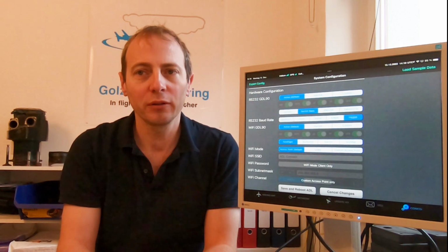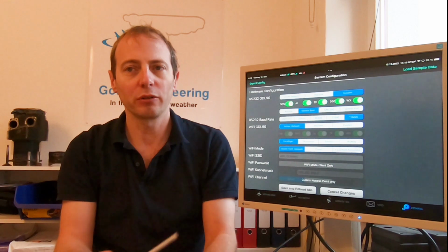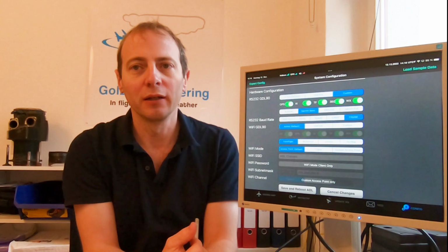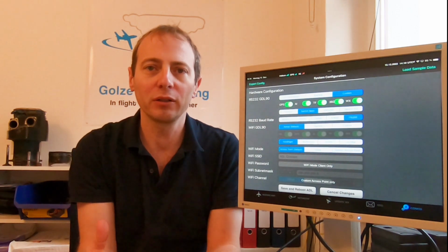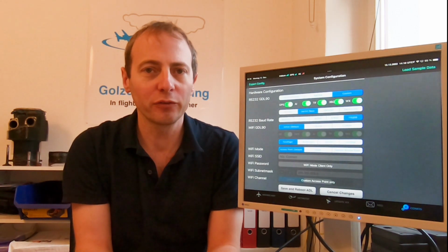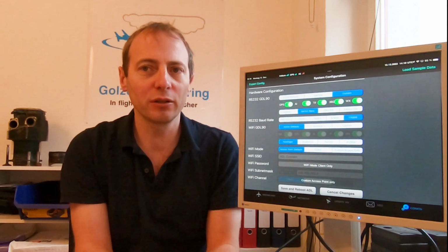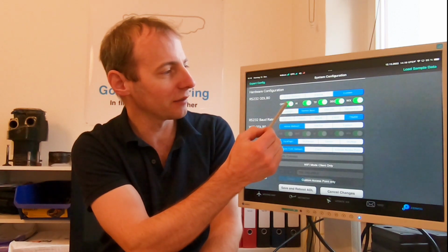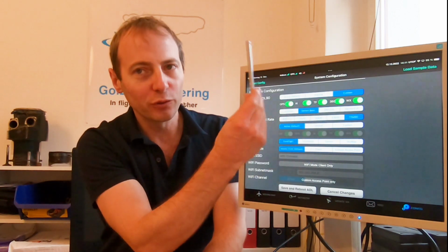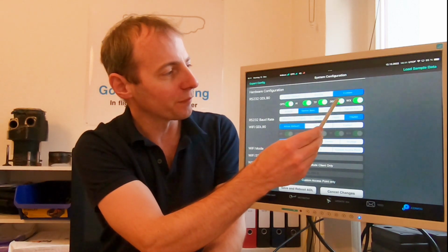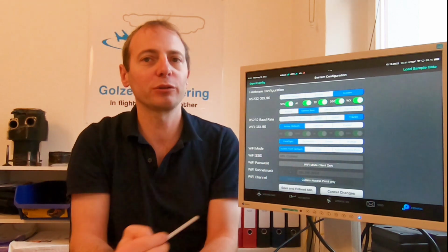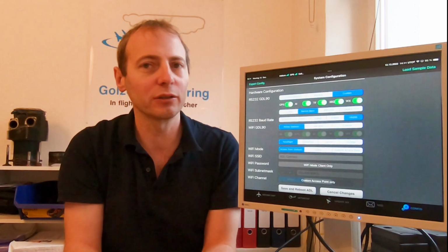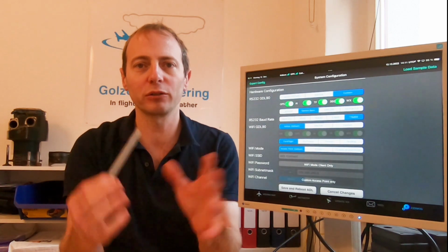In the custom mode, just to show that here, you can have special configurations on which data is output. Usually the whole set of data is outputted on this interface, but if you have some special requirements, you could restrict that. So you could no longer send the attitude indicator, the GPS, the traffic, if you have an ADL device with traffic, the 360-degree traffic, which means non-bearing ADS-B targets. And you have the actual weather data, and you can configure which is outputted.